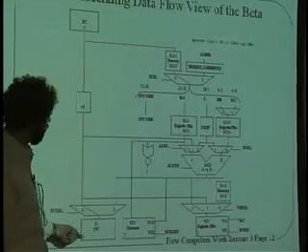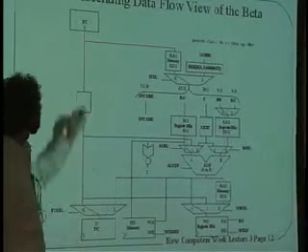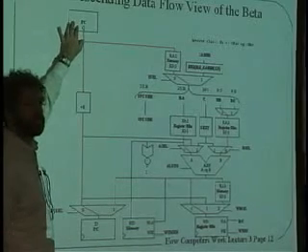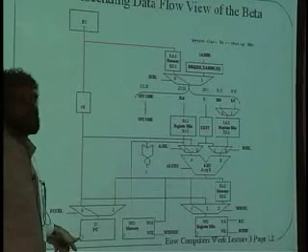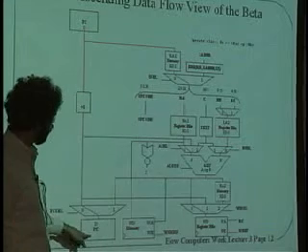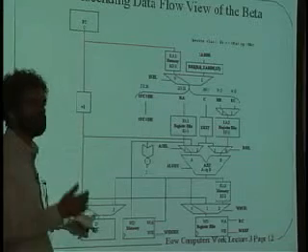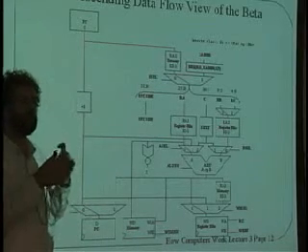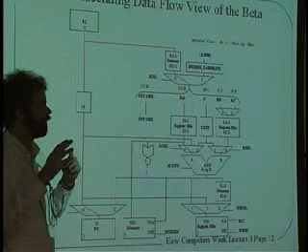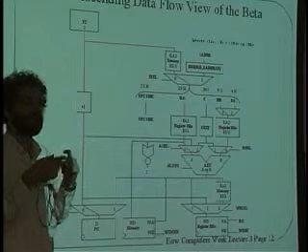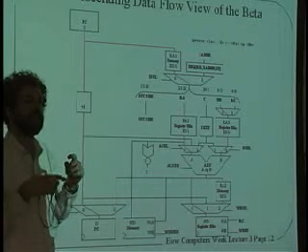And then when this clock goes off, it will snap a copy of the data here on D. And what is the result? If the PC had a particular value n before, when this clock goes off, what will be written into the PC is n plus 1. Now, notice that as soon as the clock goes off, n plus 1 begins to race around here and turn into n plus 2, and then pretty soon what's in front of the lens of the camera, which just took a picture of n plus 1, suddenly morphs into n plus 2. And so you may think to yourself, oh my God, did it take a picture of n plus 1, or did the data run around and become n plus 2? Or maybe n plus 3 if it went around a few more times, or n plus 4, or n plus 5.